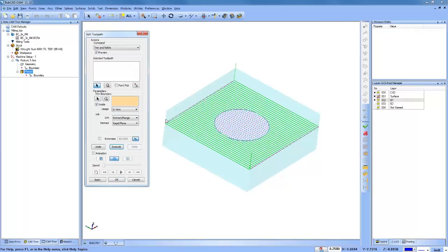And what's going to happen is where it runs into this void, instead of going to a clearance, we're just doing a rapid move. Okay, so the tool would move along at a rapid rate as it relinks. So again, these are areas where you can optimize your toolpaths depending on different scenarios.